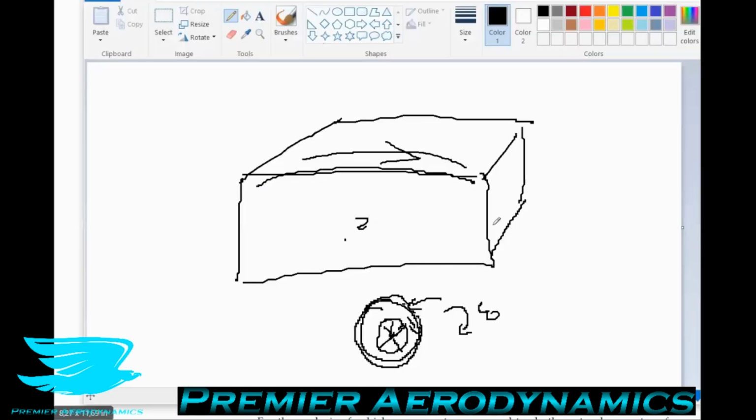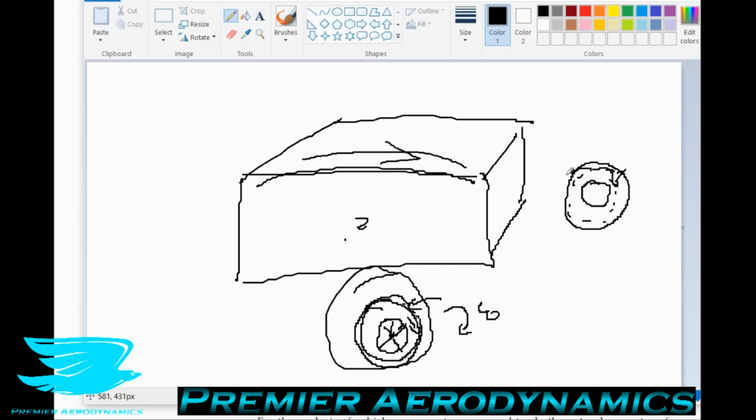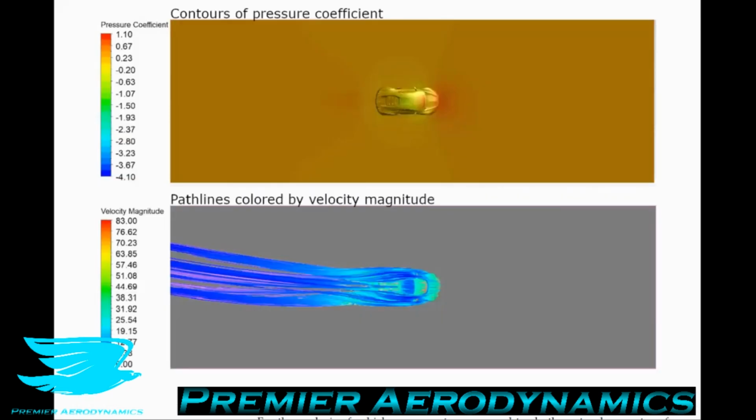So what I can tell from that description, for the wheels, I think they're using a rotating wall condition. So what this does is you literally just have whatever object you want to rotate, let's say your wheel, and you say, okay, on this surface, we just have this rotation occurring on the surface, not the cell volume. So in this MRF situation, you have the entire volume surrounding the wheel. On this, you're just looking at the surface of the rotating wall condition. That's the difference. The rotating wall condition is significantly cheaper to do computationally, and was before the MRF approach. Both of them are somewhat outdated these days. The sliding mesh is often the next best thing, but rotating walls and MRFs are good in certain situations.